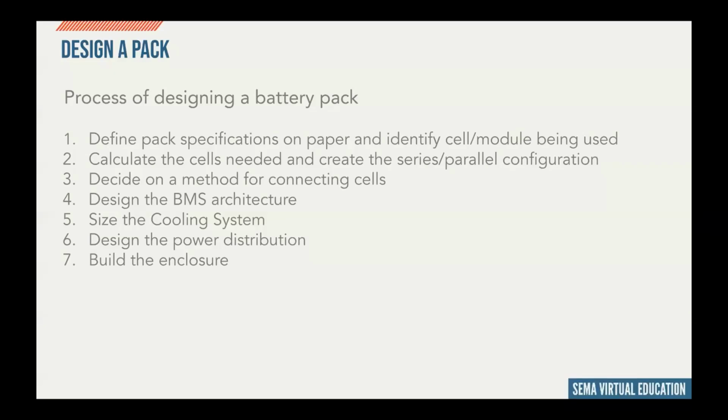So the next step is to decide on a method for connecting the cells, and this is very cell dependent. If you're using a prismatic cell where you can bolt bus bars together, then you're going to use a bolted bus bar configuration. If you're using pouch cells, you're probably going to be using laser welding. And if you're building in small volume and cylindrical cells are being used, then you're most likely going to be tab welding the cells together.